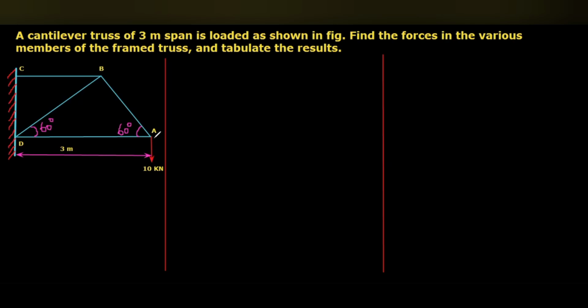So directly we can analyze by drawing the section line. In method of joints, we go directly to the corners, like each joint. In method of sections, directly we can go for the section line and analysis. That means reaction calculation is not needed here since there is no reaction force, as we discussed in the simply supported frames.